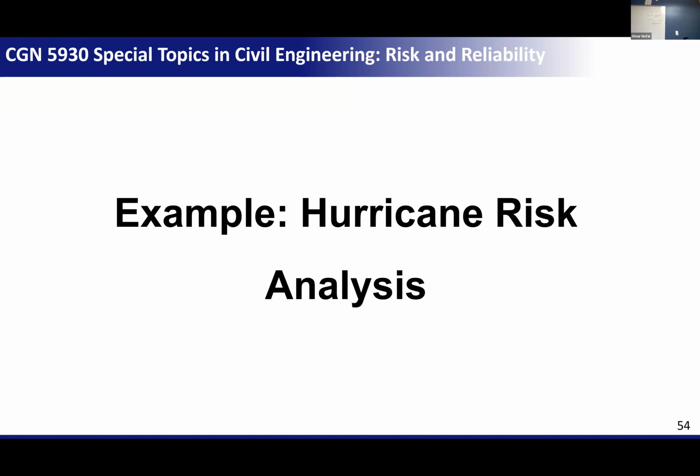What else? Waves. Storm surge usually doesn't cause structural damage because it's a static flooding, unless it goes with a high velocity. But what causes structural damage is a high surge with waves on top of it. These waves act like an impact force that can cause structural damage to buildings on the coastline. So the combined impact of storm surge and waves is also one of the hazards that can cause structural damage. Do you have any idea what indirect hazards hurricanes might bring?